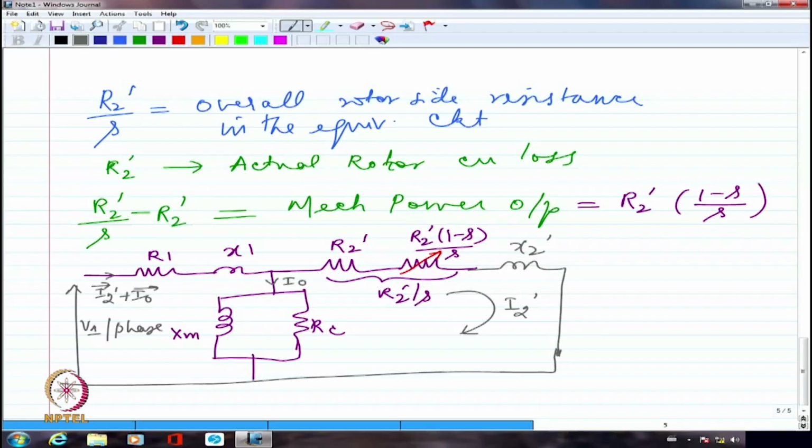So I will never ever have an induction motor work at unity power factor. I will never ever have an induction motor working on leading power factor. It is an inductive effect always. I will need that current no matter what to establish the flux. And if I am establishing a flux, it is inductive.